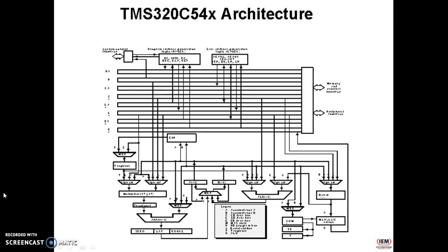They carry the addresses needed for instruction execution. The C54x can generate up to 2 data memory addresses per cycle using the 2 auxiliary register arithmetic units, considered as ALU0 and ALU1.